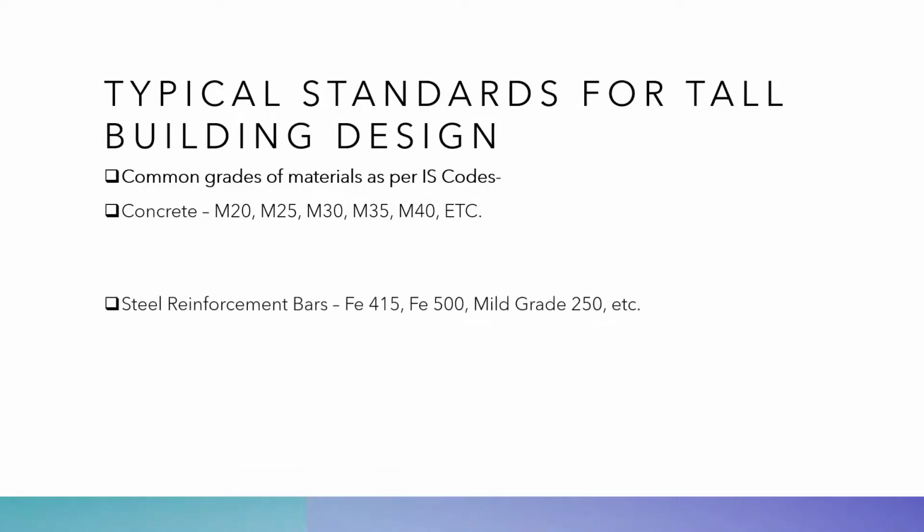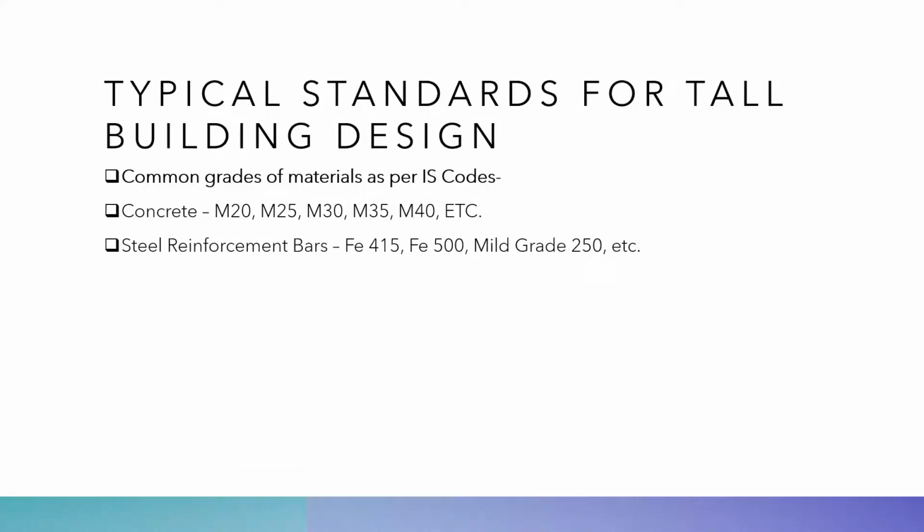For the steel reinforcement bars, you have different grades like Fe415, Fe500, mild grade 250, etc. Fe415 bar would have a minimum yield stress of 415 Newton per mm square, and so on.